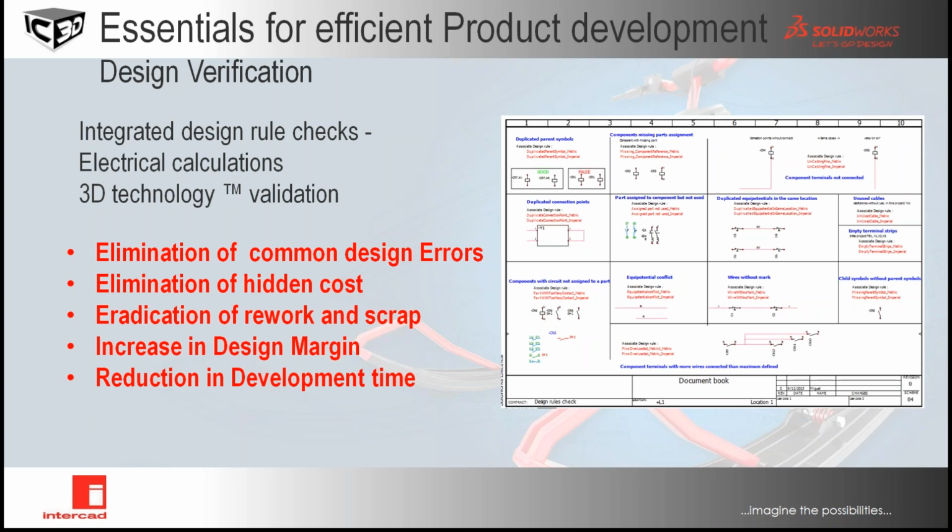It's not only just a drawing tool, it can also act as a verification tool. So, for example, if you make a mistake and join two different types of wire, 12 volt to 24 volt, it will give you a warning straight away that you've joined a short circuit. If you overuse a contactor, or if you've got some spare contacts left on a contactor, it will flag you in both situations. It can also work out the voltage drop on the cable, and a few other verification checks.